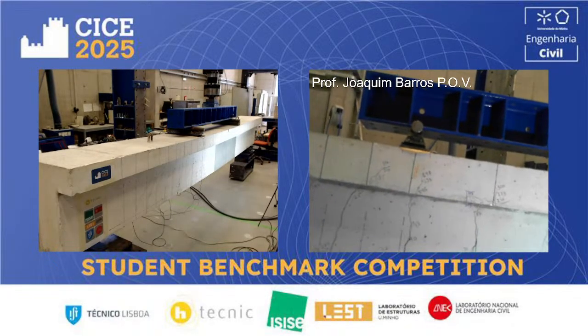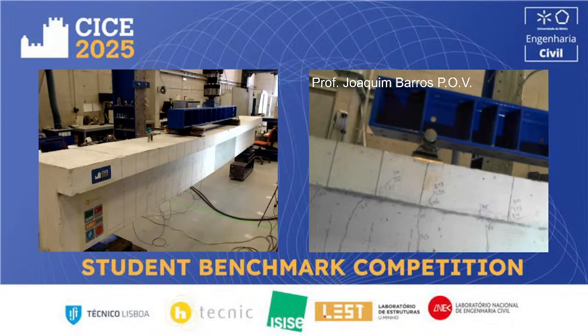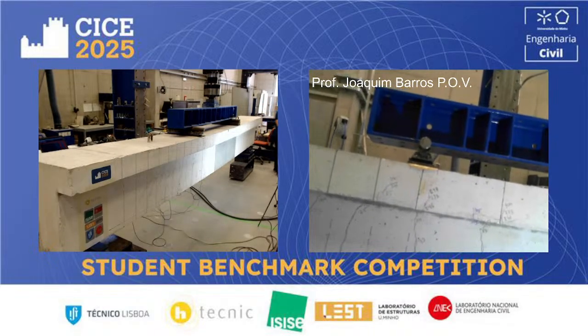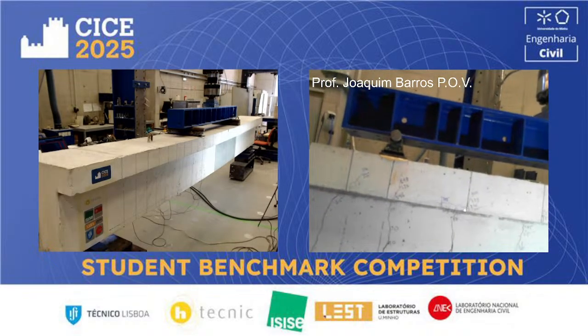And then the maximum, 340. When the laminates fail in tension, the load carrying capacity of the beam will drop to the level supported by the flexural steel bars.